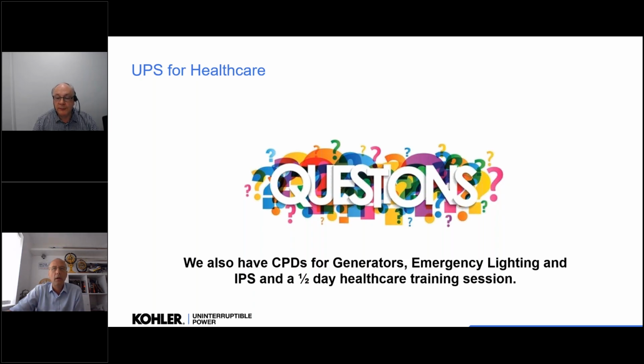Another question, what is the percentage energy loss through double conversion? That does vary from manufacturer to manufacturer. Very old systems would be 90% efficient or less. Over the years, we've greatly increased the efficiency of UPSs, and with the very modern UPSs, we're looking at over 97% efficient online in VFI mode.